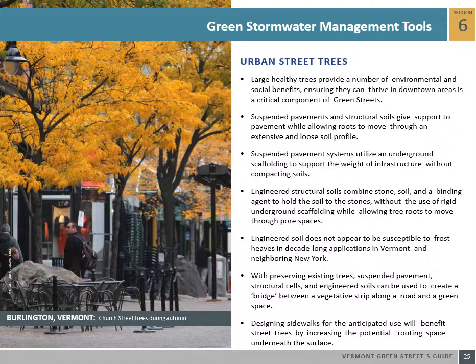Urban street trees typically cost between $150 to $600 per tree, depending on size and species. Total cost of a tree depends on caliper and whether structural soil or suspended soils are used. It is common for structural soil to be used more now in urban environments, with a line item for the tree and a separate volume for structural soil.